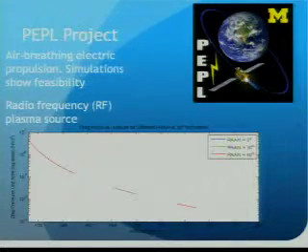The simulations were run in STK, the Satellite Toolkit. STK has the ability of outputting many different reports, such as the satellite's velocity, satellite's altitude, and the atmospheric density and the atmospheric pressure. Using these reports, MATLAB plots like the one shown here for the drag force, mass flux, and exit velocity can be made. This plot is an example of the drag force versus altitude, where the drag force was calculated using